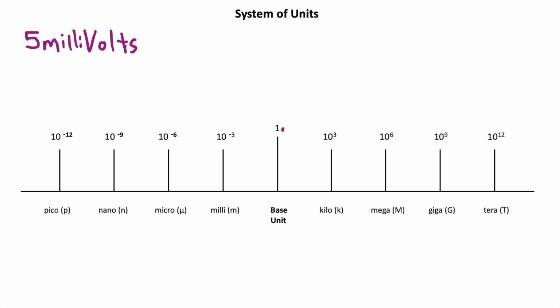One more exponent explanation: we measure things like voltage, current, or resistance in circuits. Exponents tell us where the decimal point is going to go. For example, if you have 5 millivolts, which we have written up here, and I will include the symbol millivolts here, that is 5 times 10 to the negative third volts, or 0.005 volts.